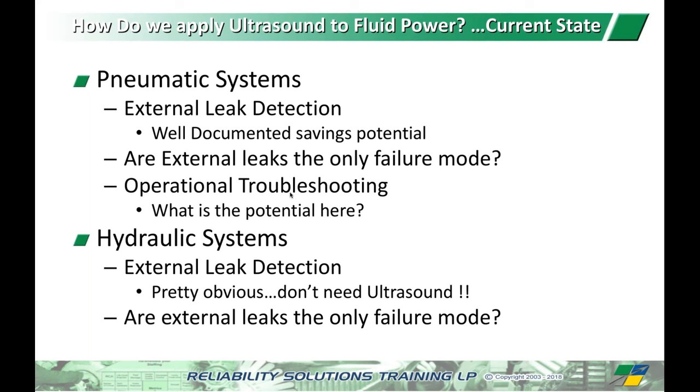And just as you check, for example, steam traps with ultrasound, a similar kind of technique for fluid power, because essentially we have a gas that's going from a high to a low pressure across a small orifice, the leaking valve, and it creates turbulence, and that creates ultrasound. And then through the magic of mode conversion and all that kind of stuff, if we get that contact probe in the right place, we should be able to detect it.